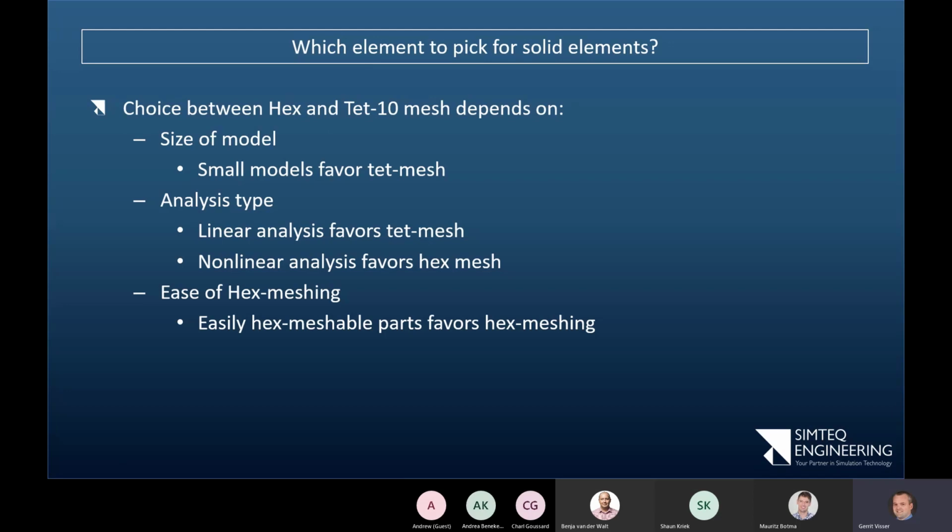Putting that into perspective again, let's assume the exponent was 1. For the same mesh size, TETs would run at least 14 times slower. So if the X mesh non-linearly ran in a day, the TET mesh would probably run in 2 weeks. I can make the same argument for memory usage. For the memory usage, the TET mesh will have at least 14 times the memory requirement for the same edge length.